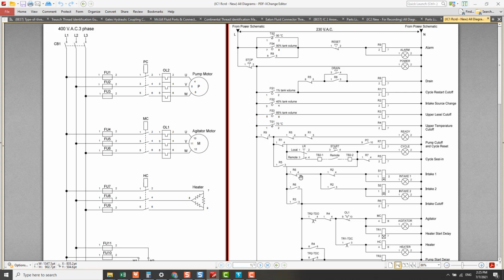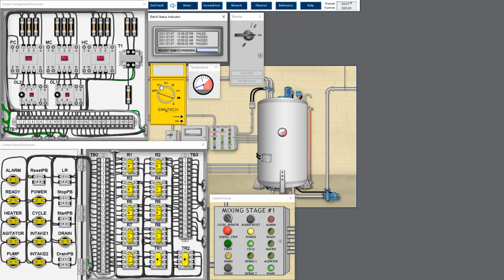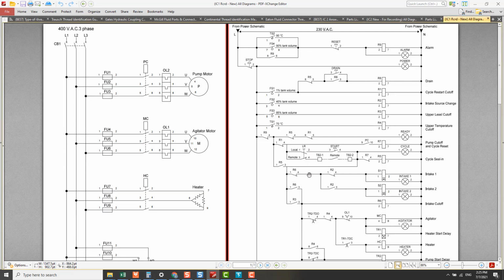Okay, R6.4. So we measure the voltage at R6.4. Okay, there's a voltage here. That means it did not trigger to open as it should. So most likely it is an internal short circuit. So we need to replace it.